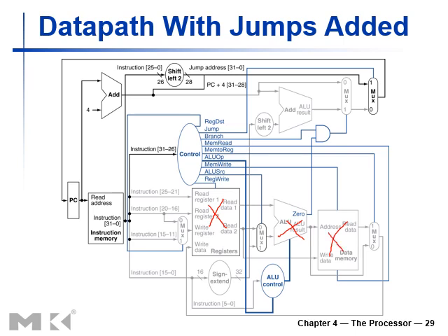So this is the fastest instruction, and in that particular scenario, when we fetch the jump instruction, we get the 32-bit machine code here. We apply the opcode to the control unit, and whenever the control unit sees that it's a jump instruction, the control unit will set this jump signal equal to 1.